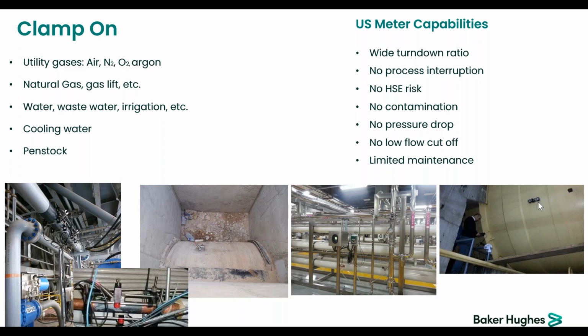I don't have the photo here, I didn't put that one, but we also did a test in France with EDF, which is a national energy supplier, on a dam, and they were changing the switches, the flow switches. They were mechanical flow switches, and because they were breaking them once every few months, they wanted to get ultrasonics, and what they were not sure of is the maximum capability velocity-wise. Our system is normally designed to handle, in feet per second, about 36, close to 40 feet per second.